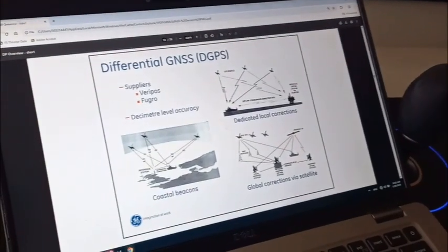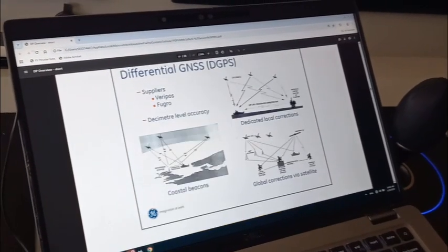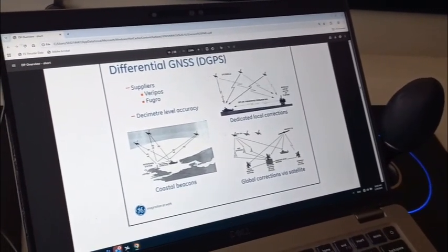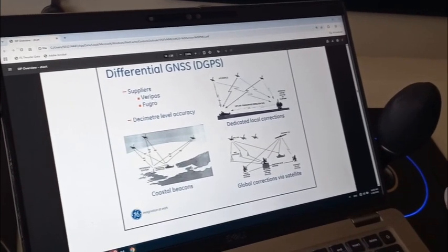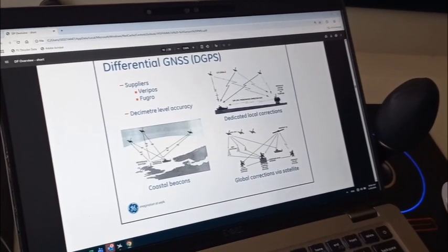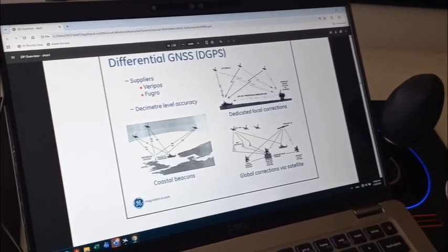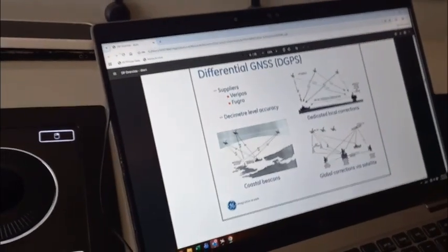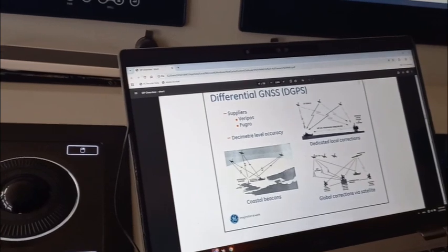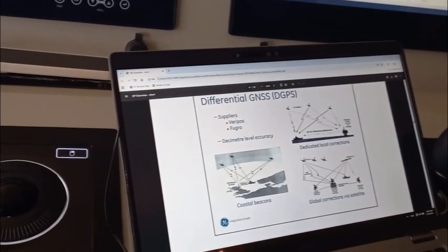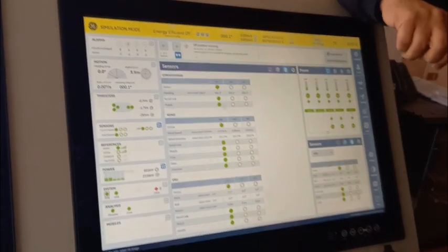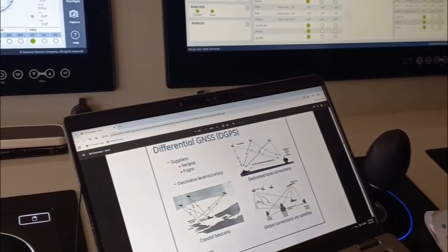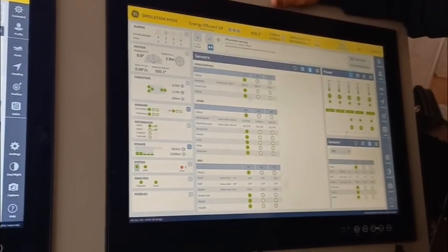Or they can receive it from the station. I need to ask you a question regarding DGPS. Last time you told us how to renew the subscription. In Kongsberg, in K-Pos, for the DGPS that we have, we can change the satellite from the display later. Here, how can we change the satellite after subscription if we need to? I can show you later, but you will have to connect the laptop to the receiver to access the menu.